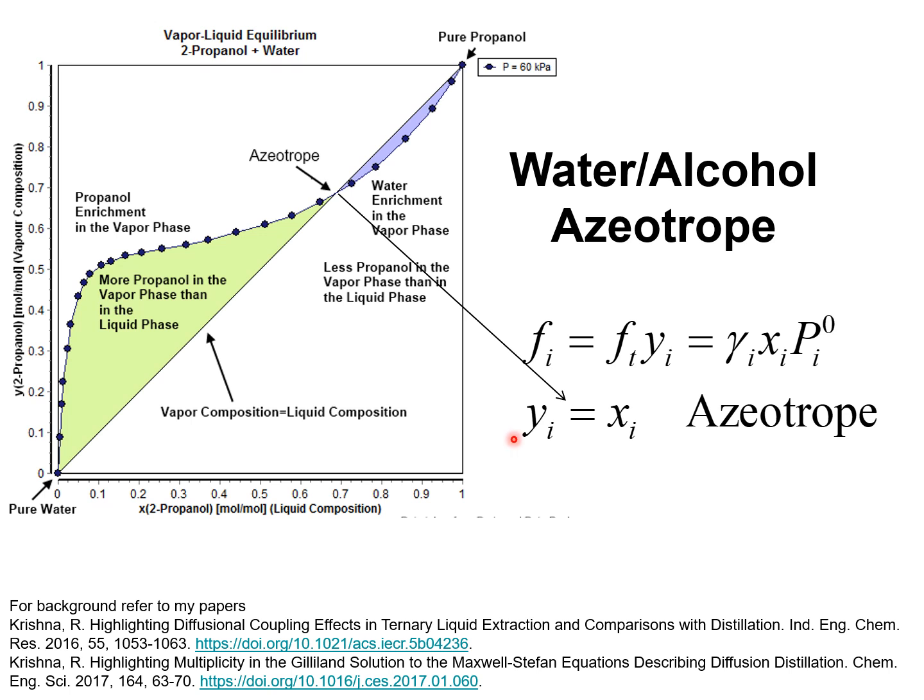The separation of water alcohol mixtures by distillation is often made difficult due to formation of azeotropes. And in industrial practice, purified alcohols that are demanded by industry requires the use of entrainers such as cyclohexane or benzene in order to alter the vapor-liquid equilibrium.